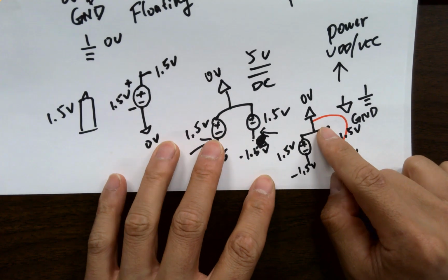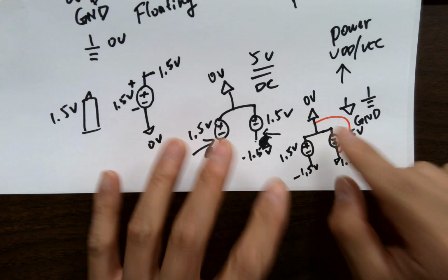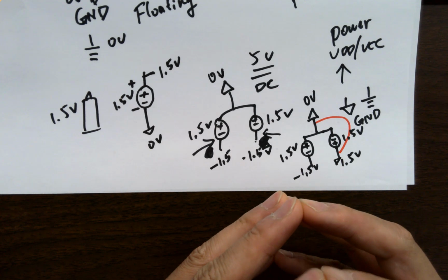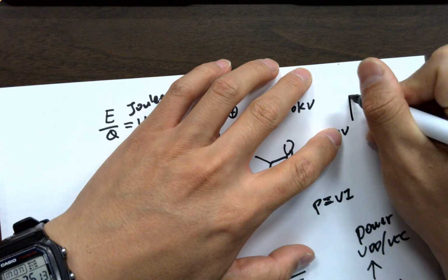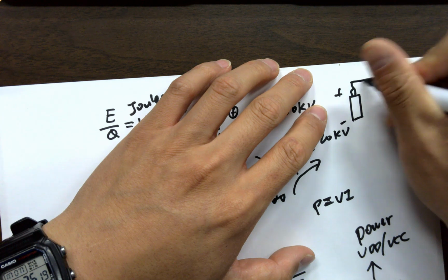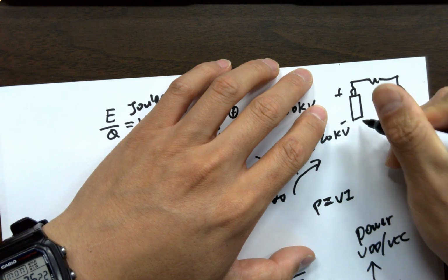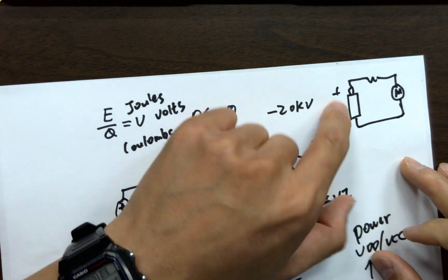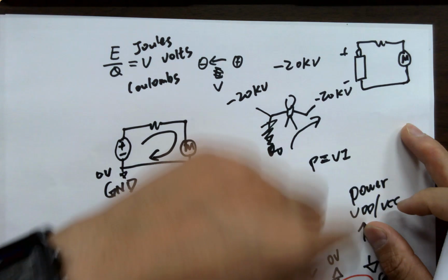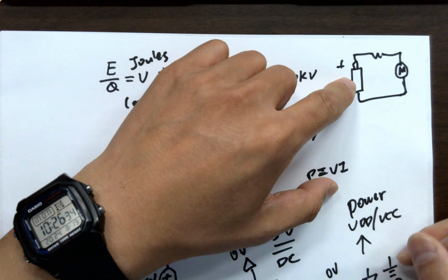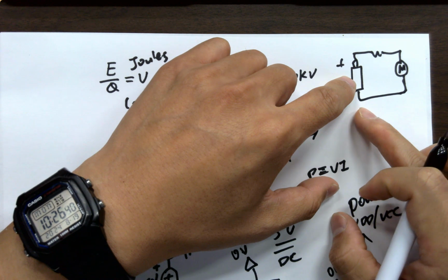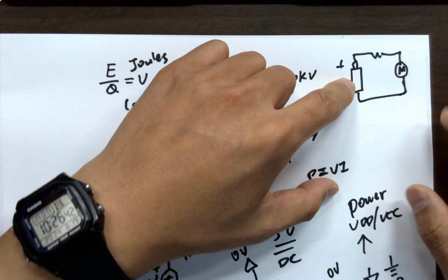Let's just think about real circuits. There is no physical part called ground. It's not a piece on the circuit board. If you grab a battery, it's plus and minus, and we connect it to the resistor and the motor to spin the motor. We just build a circuit like that. You can see a lot of examples like this in this class because they didn't draw any grounds. But whenever you get into the lab, you have to deal with grounds. A lot of textbooks don't draw the triangle, which is not right, but they probably don't want to confuse students, like what I'm doing here.